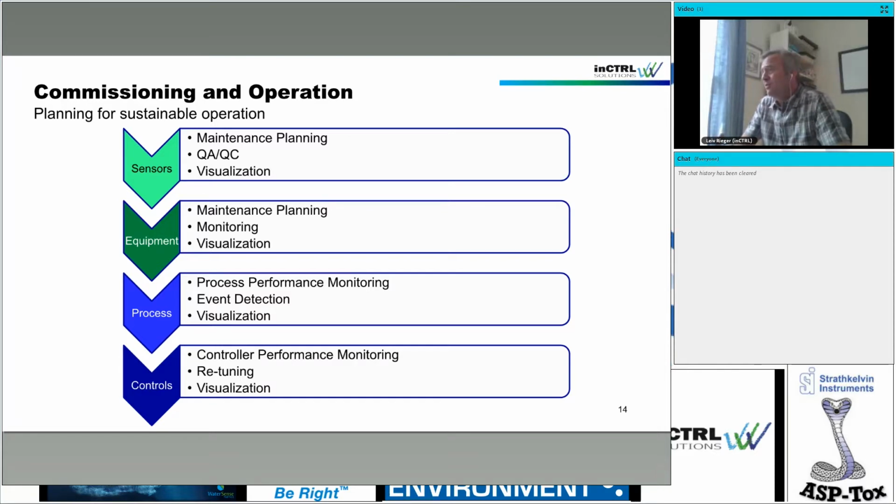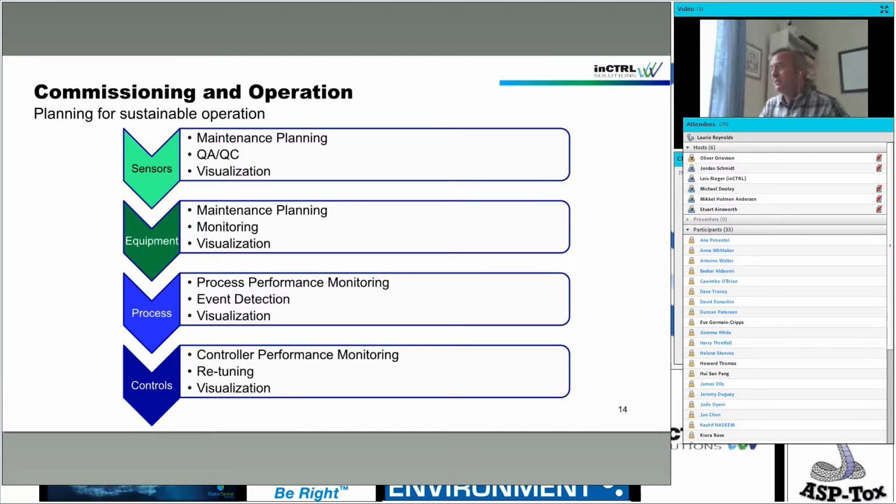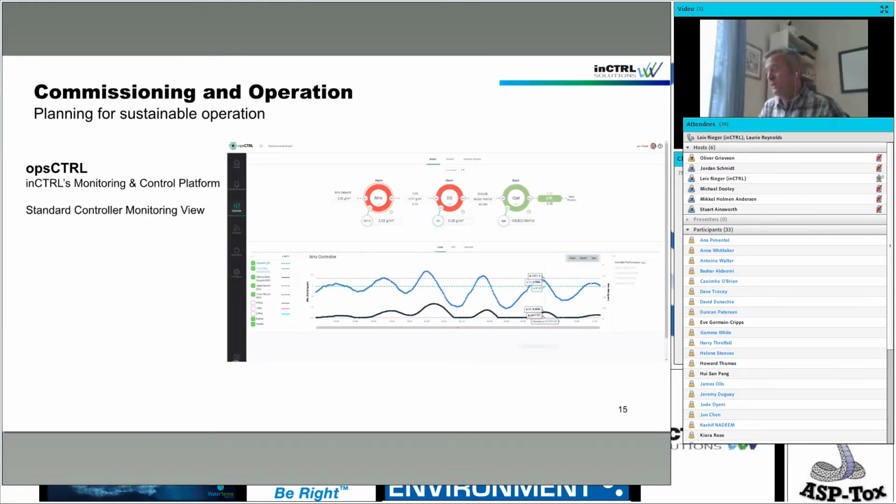So we have developed a number of controller performance metrics to be able to monitor that at all times, indicating if better tuning would improve performance, right? So that's very important to understand. Tuning is not helping all the time. So if the controller is sitting at a bound, the best tuning would not improve, right? Because the controller is not active at all. So sometimes you have to go outside your controlled system and change the sludge retention time, for example. Yeah? A couple of examples before I wrap up.